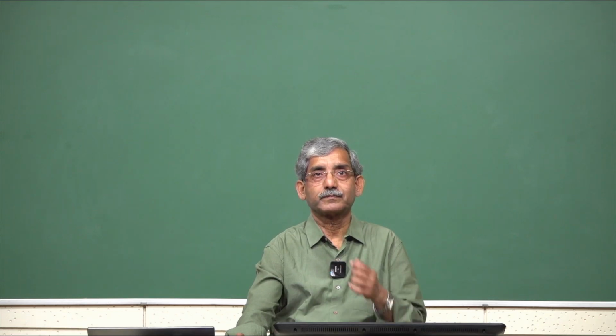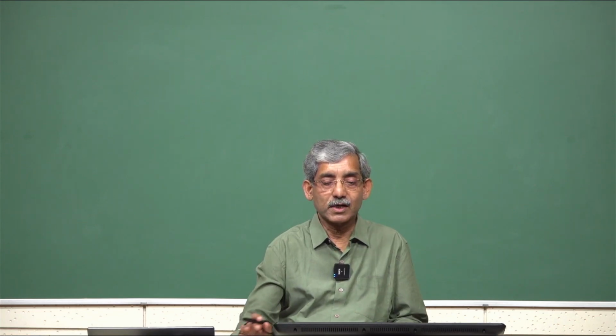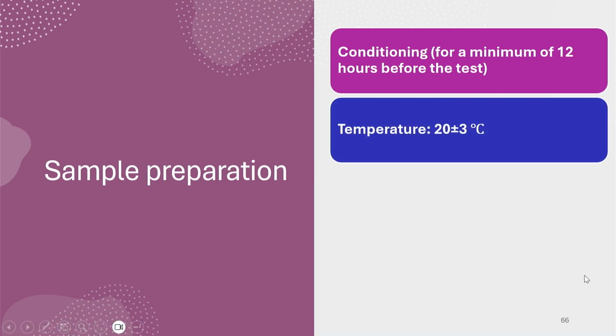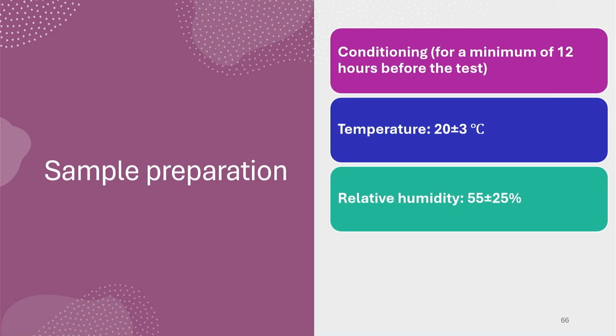Now, the sample preparation. Conditioning is there. First, samples are conditioned for a minimum of 12 hours before the test at a temperature of 20 plus minus 3 degrees Celsius, at relative humidity 55 plus minus 25, as per the standard.